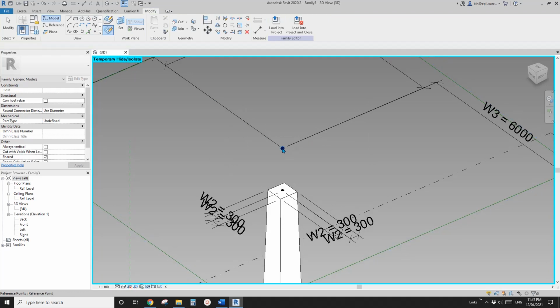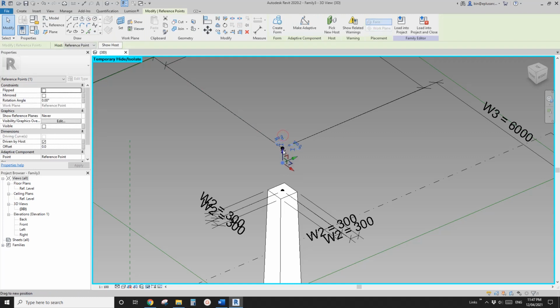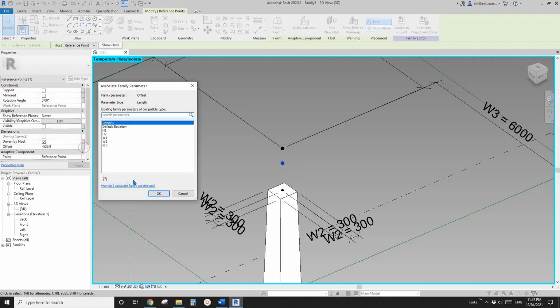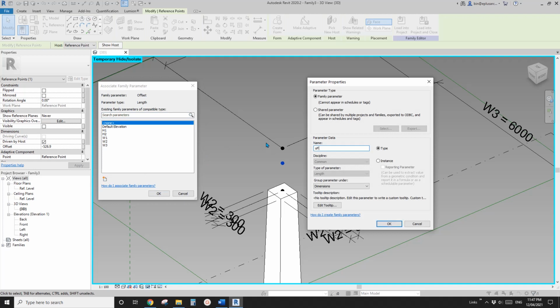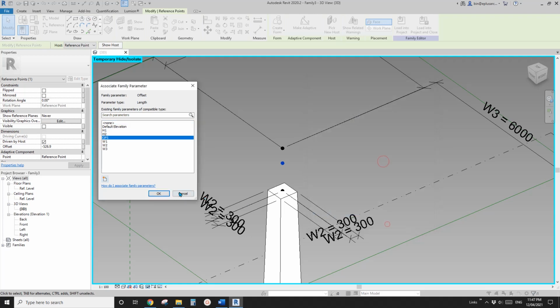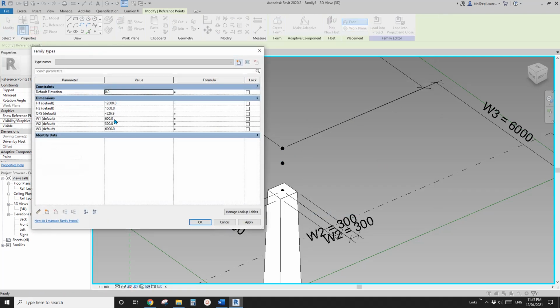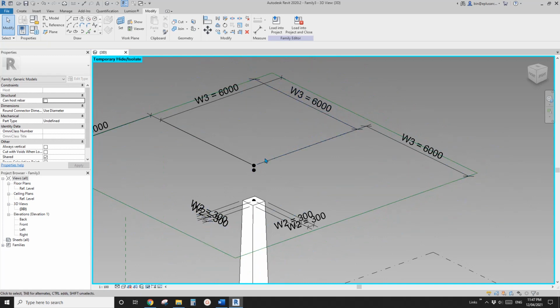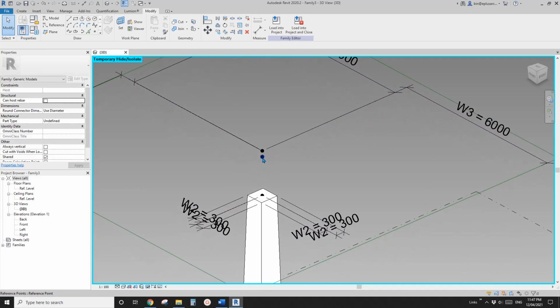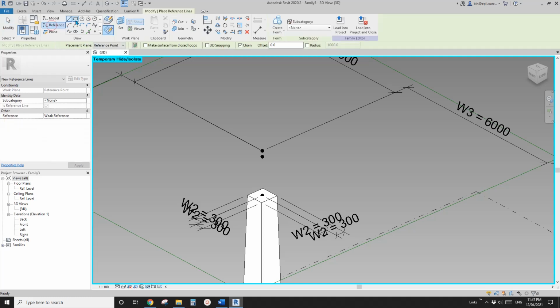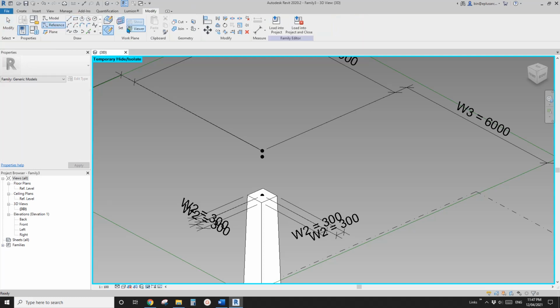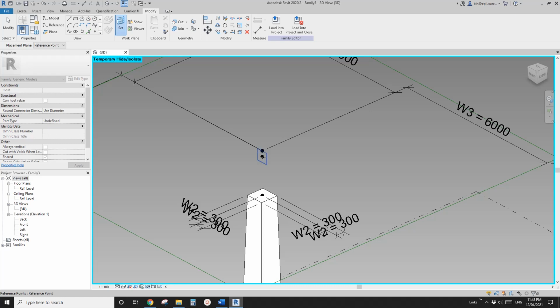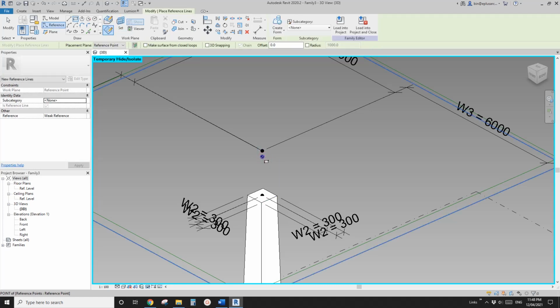Okay. So now select this point and go down. This time I'll create an offset parameter instance. I know maybe I need it to be -200. Depending on the height difference, you might need more. On this point, I'm going to create another rectangle, draw on work plan, set work plan, pick the horizontal work plan on this point, and place